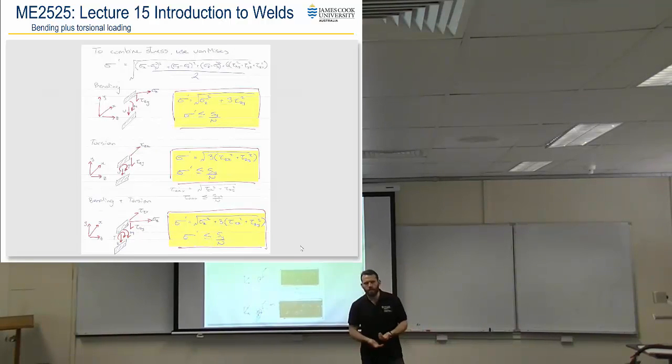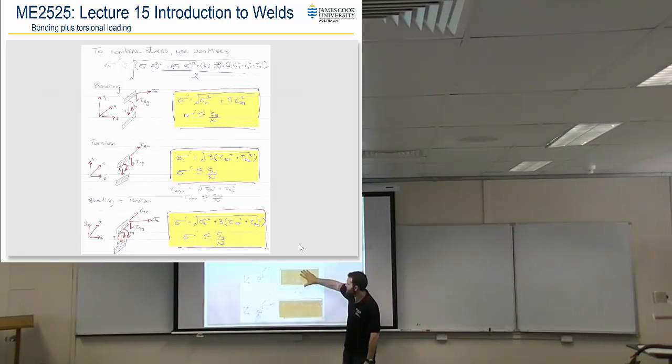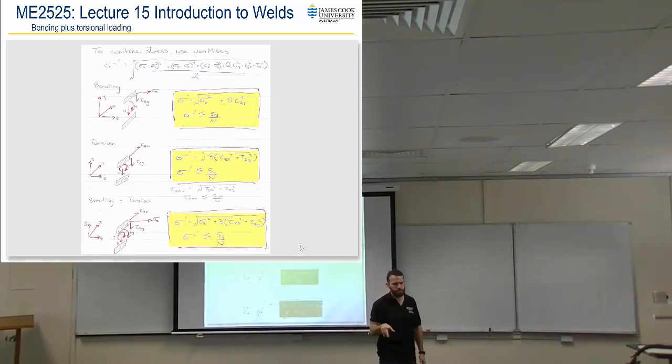You guys had a go at, or we worked on the board on, the torsional variant. The bending variant is basically identical in workflow, and the only difference is when we calculate von Mises. This is the one we did yesterday, the torsion. Von Mises is the square root of 3 times the x component and y component of those torsions squared. If you now have a primary shear and a tensile bending stress, then this is the same type of von Mises equation you're quite familiar with: the tensile stress squared plus 3 times the shear stress squared, all square rooted.